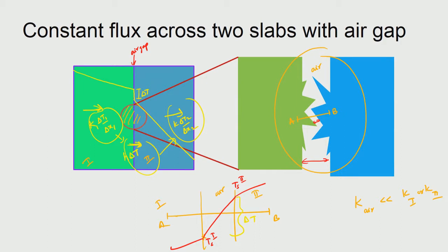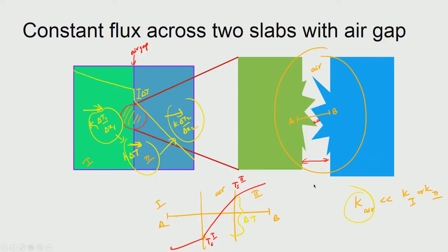In the case of situations like continuous casting, this actually plays a very big role. We do actually have this air gap between the caster and the metallic material that is solidifying, and inside this air gap we try to introduce ceramic materials to control the thermal conductivity and thereby achieve different cooling rates to avoid cracking, etc.